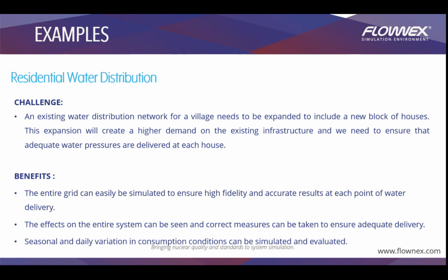The benefit we had with this was that the entire grid could easily be simulated and we could ensure high fidelity and accurate results at each point of water delivery, meaning at each house. We could also see what pressure and what flow rate we're getting at each point of water delivery. The effect of the entire system could be seen and correct measures could be taken to ensure adequate delivery as well. And we could also simulate the seasonal variations in the consumption of water.